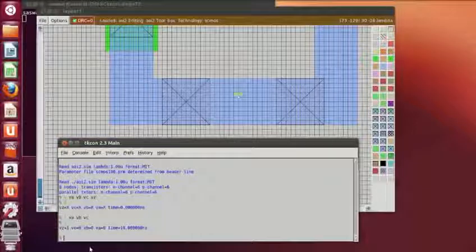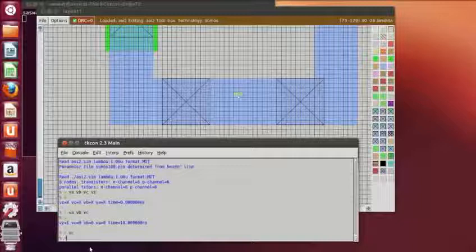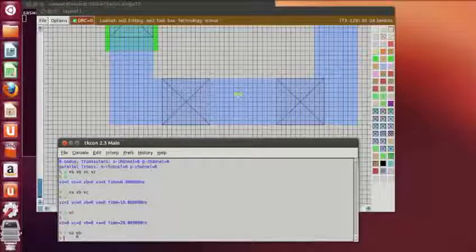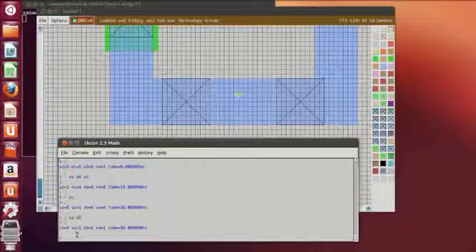Now if I give a high value to VC, then see, the output of the AND is 0 and the output of OR is 1, so the invert will be 0. If I give high value to VA and VB, then again the output will be 0.